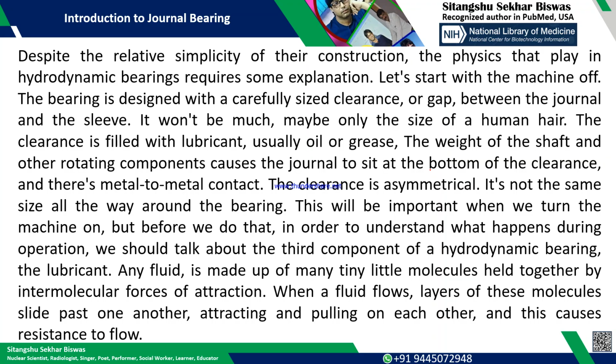And the clearance, as I told, will be filled with lubricant, usually oil, or sometimes the liquid which you are handling, which itself is responsible for generating the oil film across the journal when the impeller or the shaft reaches a particular RPM.